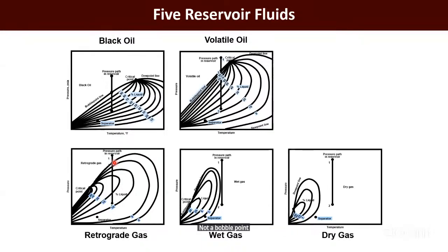The dew point is the first point where we see the first droplet of oil, or droplet of condensate. So the gas has some heavier components, and with pressure depletion, we see some oil droplets in it. Once we cut the dew point line, we start to have some liquid droplets, and it continues until we reach this line, where we cut the same line twice. So in this area we have liquid droplets, then the liquid comes back into solution.